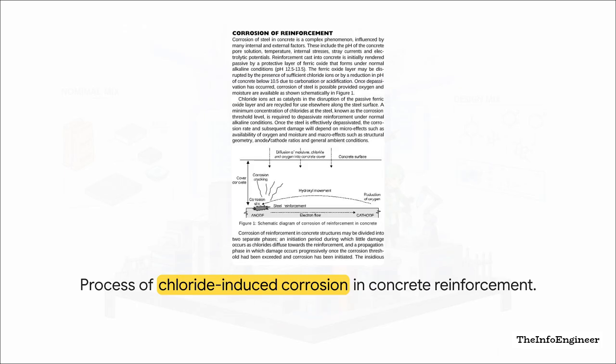Chlorides will just diffuse right through that highly porous concrete matrix. Eventually, they break down the passive protective layer sitting right around your steel reinforcement. And once that happens, it's game over. The rebar corrodes, it expands, and it literally cracks and spalls the concrete from the inside out.